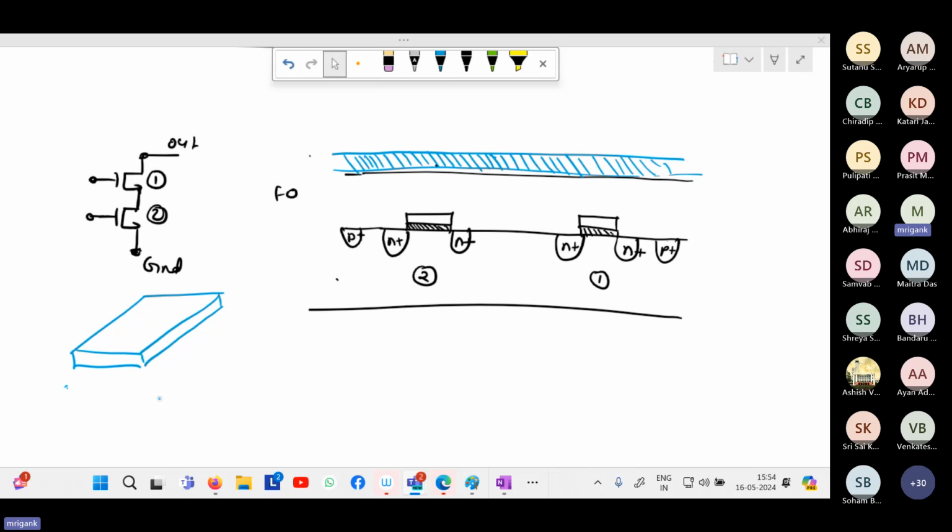So at the bottommost level, you have the silicon. You are fabricating the transistors on that silicon. In that entire lower region, you will have many transistors fabricated at different spots and locations. But now, in order to form the connections, we make use of these metal layers separated by field oxides. So FO1 separates the silicon from metal one. Likewise, FO2 separates M1 from M2. Likewise, there will be M3, M4, M5, multiple metal layers.